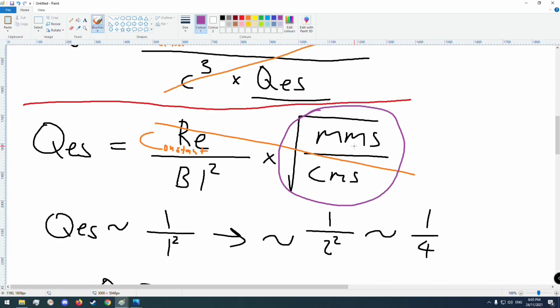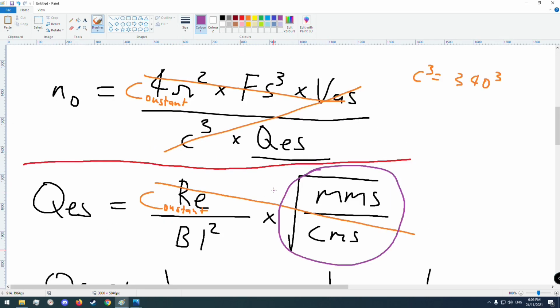A heavier voice coil increases the moving mass and decreases the compliance, which means making the cone stiffer. So a well-designed sub will take into account a high BL, and in particular subs with a really big cone area, such as 21-inch drivers or bigger, really do need a high BL in order to move the cone around with authority. If a very large sub was to use just a standard ferrite magnet, it would need to have an absolutely enormous motor on it in order to fight all the forces of the cone.